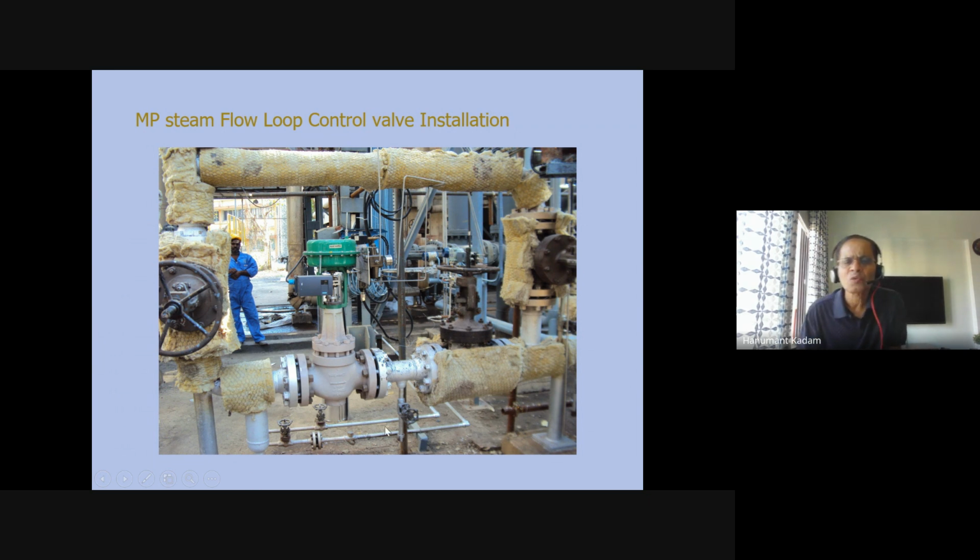And in this control valve you can see these isolation valves are there, here and here. When you have to stop the line or bypass the line from here to here, the isolation valves are also there. So in this valve you can see this is the globe body. Inside this, the plug and seat is there, the stem is there, again this link is there, this is a diaphragm.